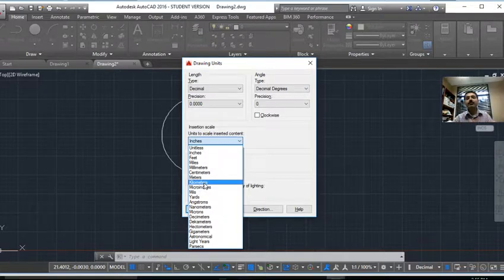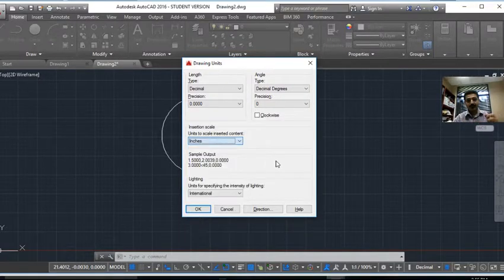Like this is my specialty as a pavement engineer, to design highways and roadways, and things are not in meters anymore. When you draw an interstate, for example, if you're driving from Tyler, Texas to Dallas, you will be driving mainly through Interstate 20. And if I want to draw Interstate 20 from these two big cities, you would be using kilometers if you are overseas, or you would be using miles all the way here if you are in the States. So you've got to set your units.